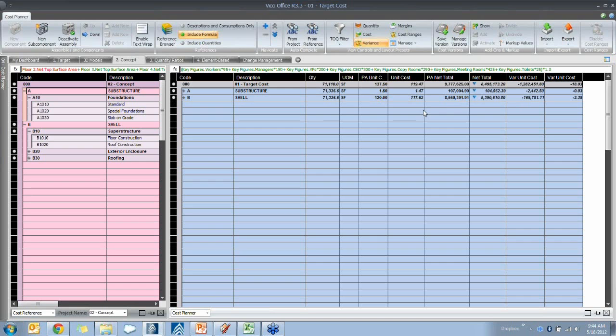Once we have used that model to generate this hierarchy of square foot numbers, we can then use our quantity ratios to generate a more detailed, as we saw in the slides, statistical bill of quantities for any elements that are similar in nature to the previous projects that we've used them in.